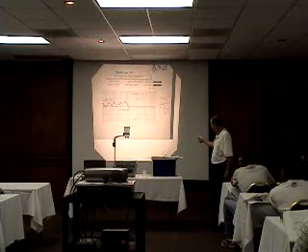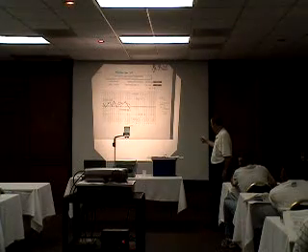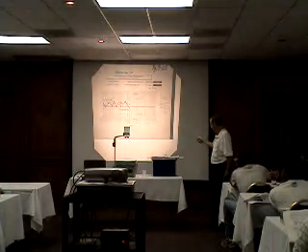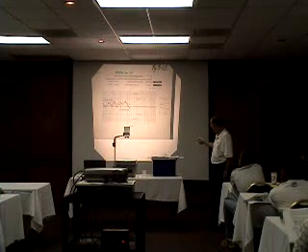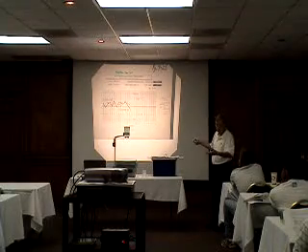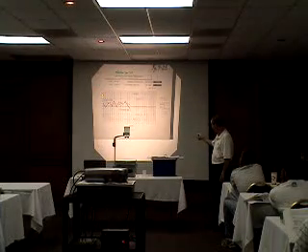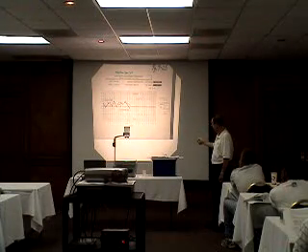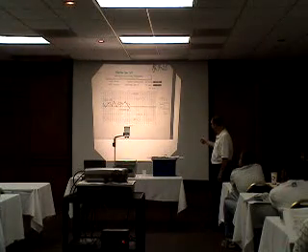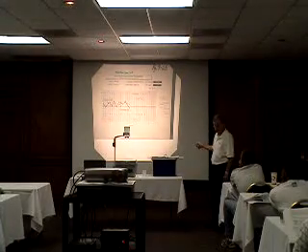We come down 1.5 and we draw another dashed green line for the bottom side of the moving average limit. And then our individual limit was 2.5, so we go up 2.5, draw a dashed red line, which is our individual limit, and down 2.5, and another red line for the bottom limit.